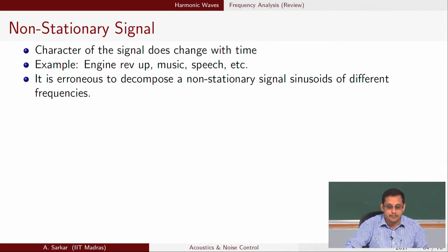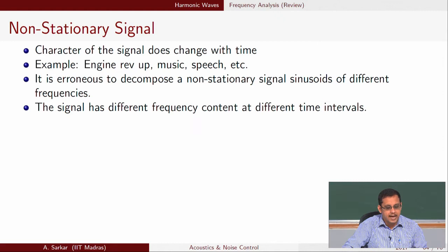As a part of one of your assignments, you will be asked to take FFT and inverse FFTs. You will see that for a stationary signal, if you take the Fourier transform and then the inverse Fourier transform, you will recover the same signal, whereas that will not happen in the case of a non-stationary signal. So, this is one way in which you can quickly identify the difference between a stationary and a non-stationary signal. In other words, when you are dealing with a non-stationary signal, you should not use Fourier analysis techniques without applying your mind.